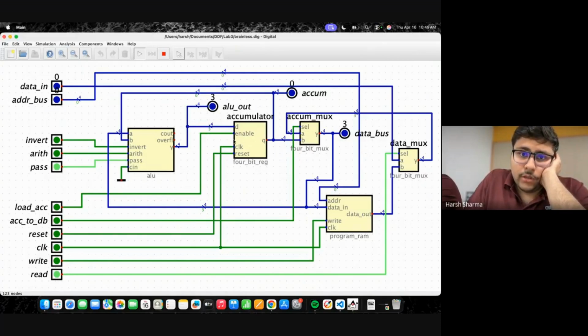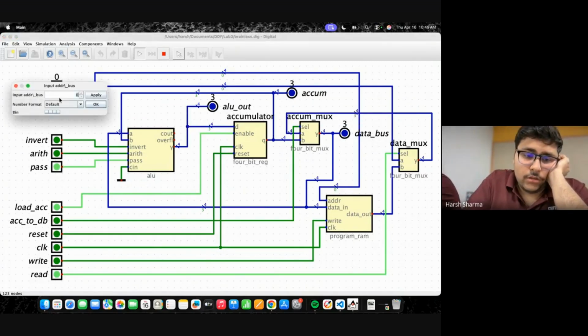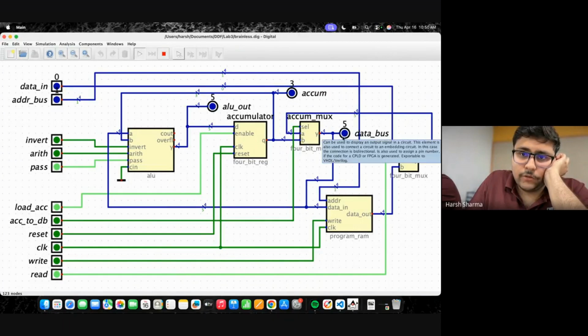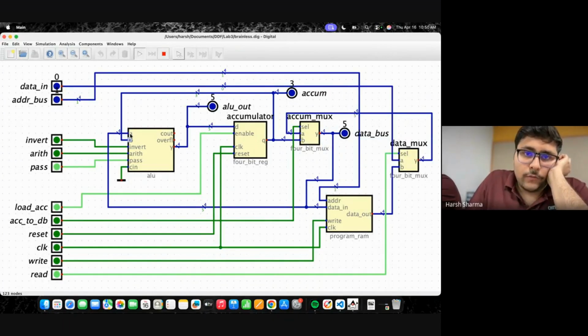This goes to the 4-bit register, which is the accumulator. So we just enable it, load accumulator, give it clock pulse 0 to 1. So we have 3 at the accumulator. So now let's do 5. Let's take data address 1. Data address 1. This goes to here. Data, it reads the data out as 5. So this goes here. B displays at the output, which is 5. 5 goes to A. Since select line is 0, we get 5 as the output. Data was 5. This goes all the way back to A. So right now we have 5.